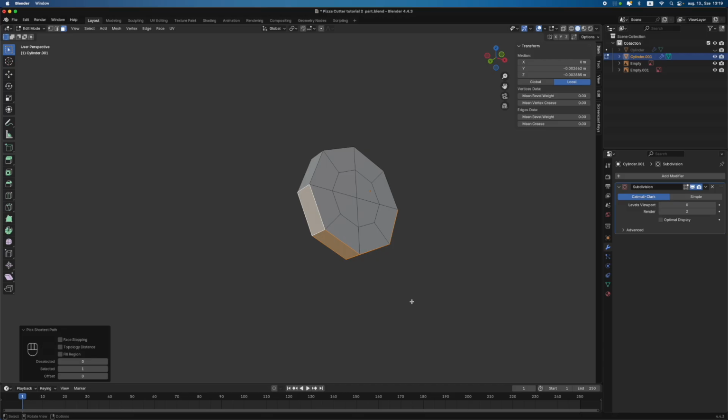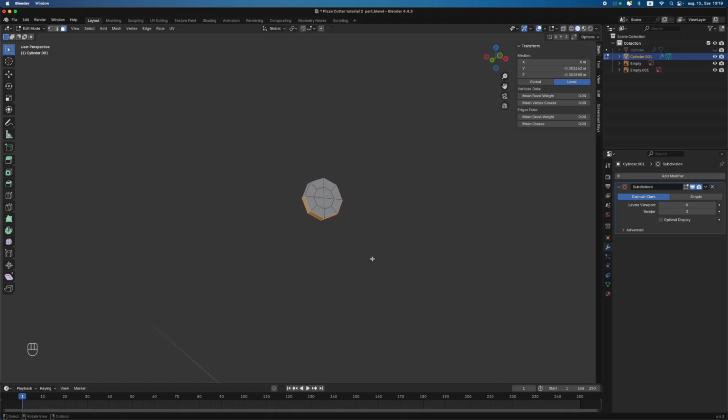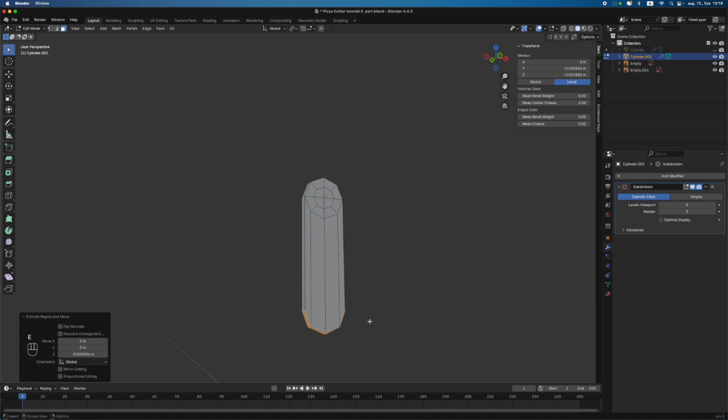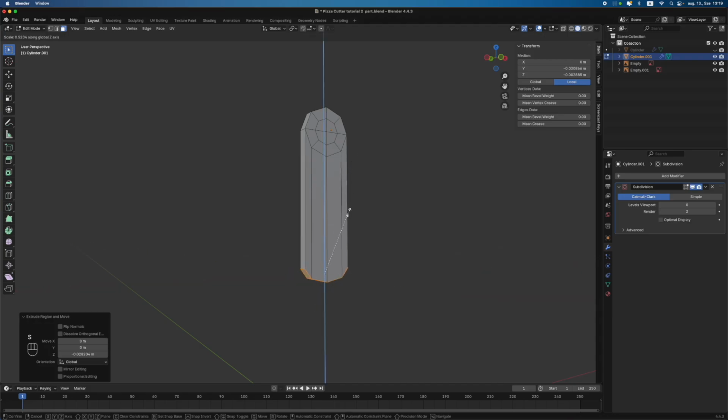So I'm going to do that, and if you want to add any selection to this, you can hold down Shift and add in these. With Ctrl you can disable these. Now we want to extrude it down, so I'm going to do that by pressing E and extrude it down, and we want to scale it in the Z axis 0, so press S, Z, and then 0,